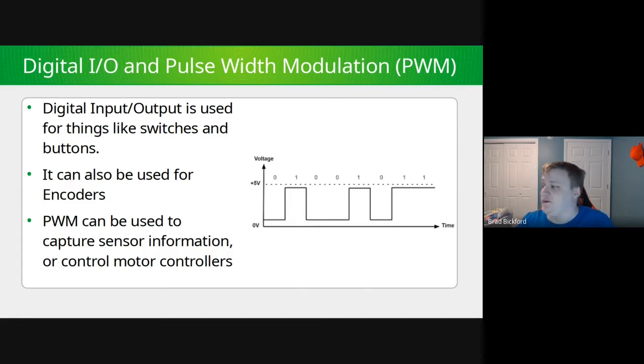There is an alternate system that we use now, which we'll talk about later, called CAN. But with the vast majority of motor controllers that we have available to us today, you can still use PWM to control them. It's just not done as commonly because there are other ways of doing it now that are, quote unquote, better, I guess.